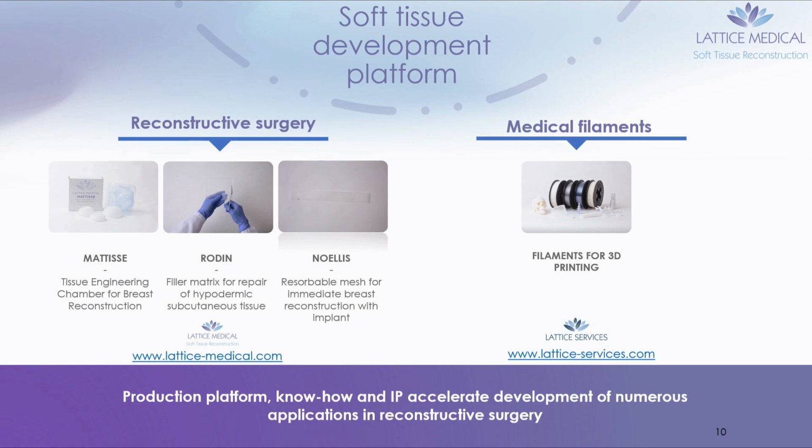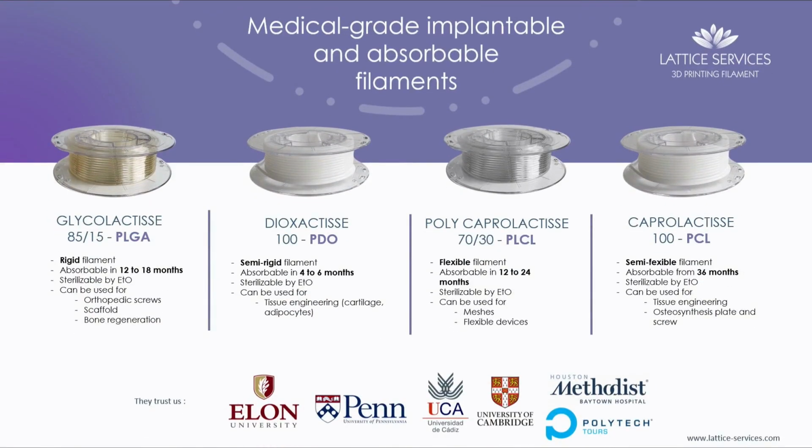And we have also developed medical filament for 3D printing, and it's branded Lattice Services, a commercial brand of our filament. And we have two kinds of filaments: absorbable filament, medical grade, with different kinds of polymers. PLGA, which is strong and dedicated to bone applications. PDO and PLCL more dedicated to soft tissue applications with different resorption rates, and the caprolactone also. And for the moment we work with universities in the development of several medical devices.